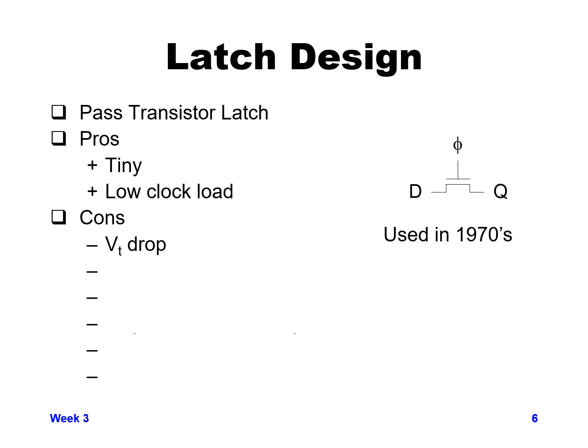This of course has several cons. One con is you're only using an NMOS transistor to try and drive both 0 and 1. So if you're trying to drive a 1, you get a threshold voltage drop at the output, and so you don't get a full VDD value out, which is a big con.